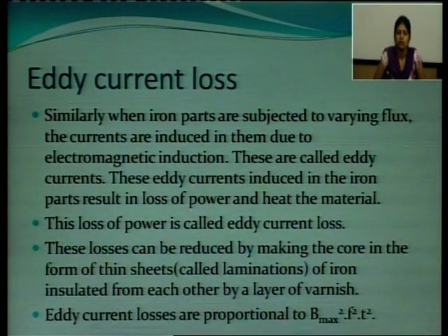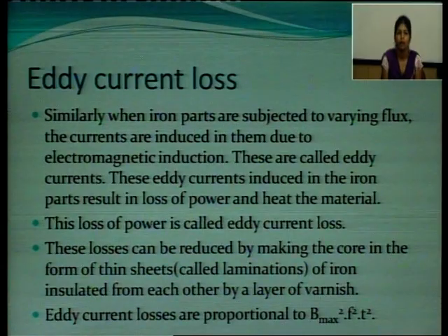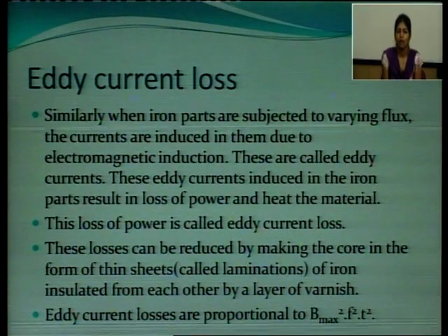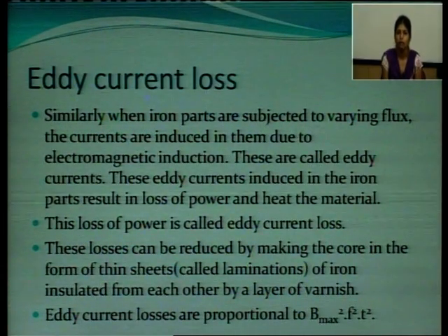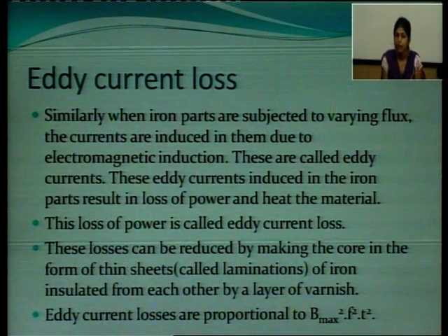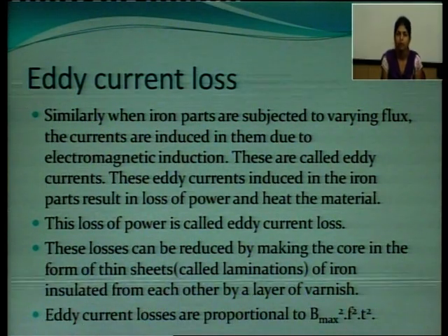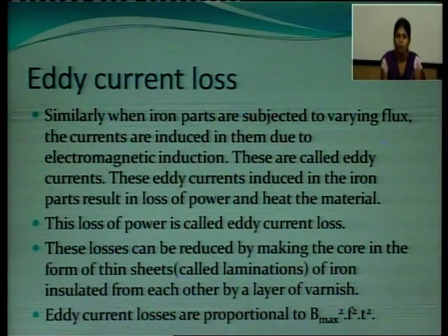The next is, let us define what is eddy current loss. Similarly, when iron parts are subjected to varying flux, currents are induced in them due to electromagnetic induction. These are called the eddy currents, and these eddy currents induced in the iron parts result in the loss of power and heat the material.